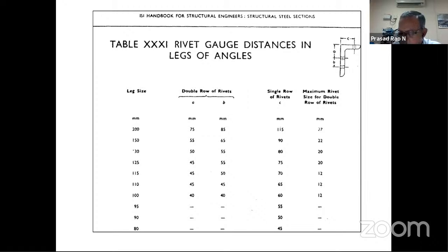And an angle section is an open section. We cannot apply the loads on the CG. The loads are applied to these flanges, away from the CG, and it creates biaxial moment. These things are taken into account in the codal books by reducing the stresses, thereby increasing the allowable slenderness ratio. Slenderness will be increased, and your stresses will be brought down so that it will be safer.